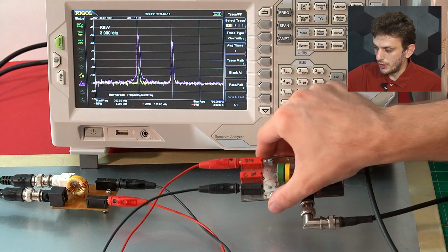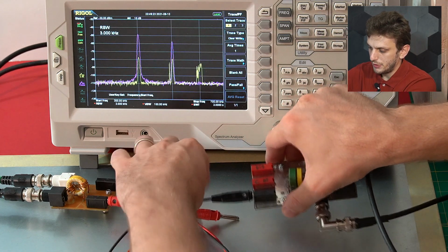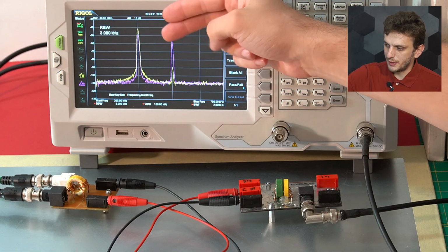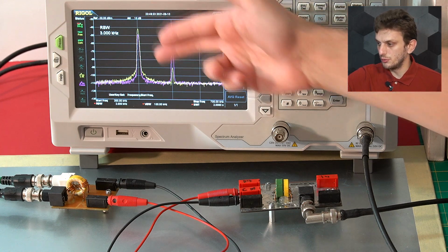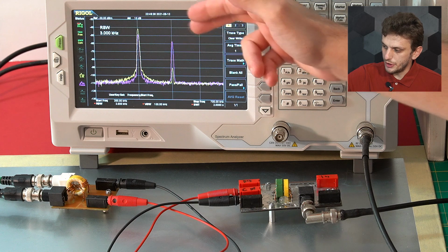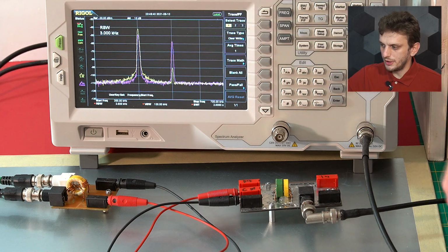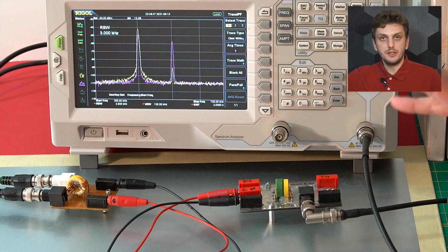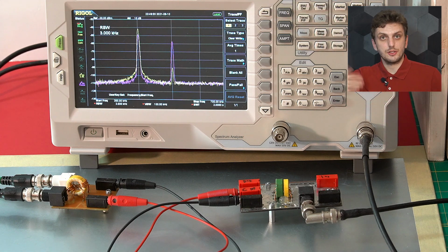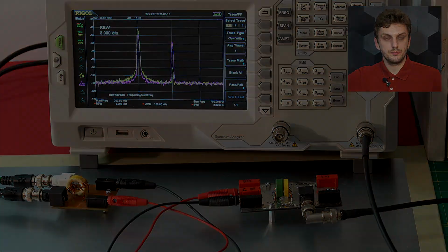Now if I swap around the inputs, so plug my input into the common mode signal, we can see our left spike even larger than before, almost 10 decibels larger, but our differential mode spike is more than 30 decibels lower. So by using the separator, we can clearly make a difference between the two spikes and the initial LISN measurement. So we can clearly extract what is common mode, what is differential mode.